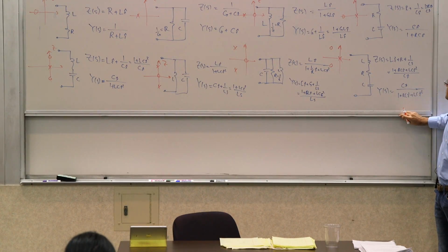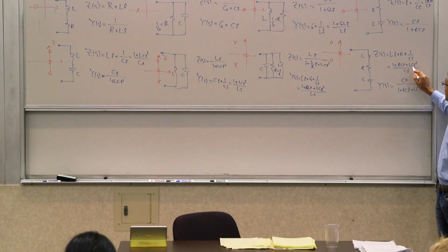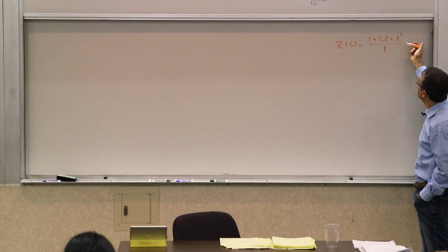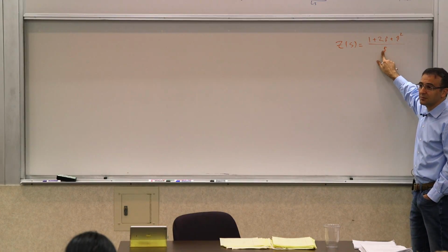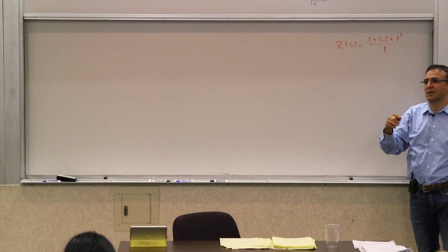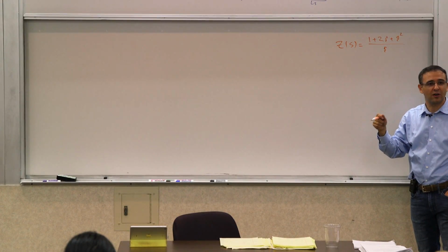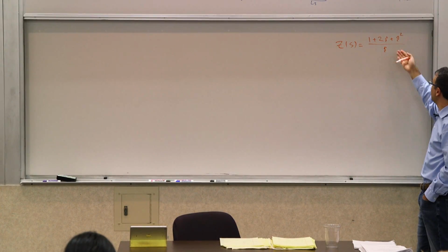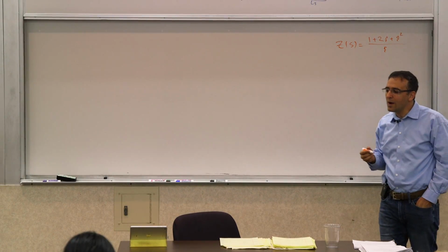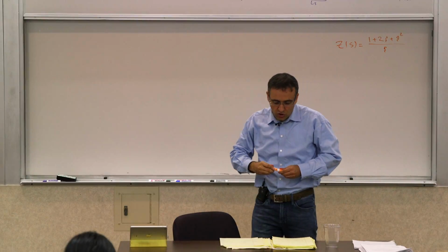Now you have to see, can you define the R and the C and the L in such a way to get these three numbers? And you should be able to, because there are 3 degrees of freedom here and 3 degrees of freedom there. Your numbers may not work out to be beautiful, and they generally aren't, but you can get something that way. But what if you were presented with something a little bit more general, more complex?